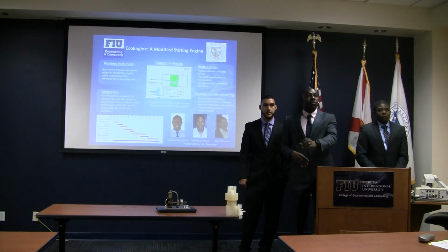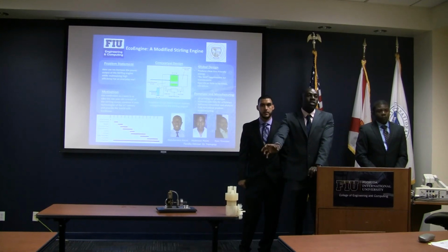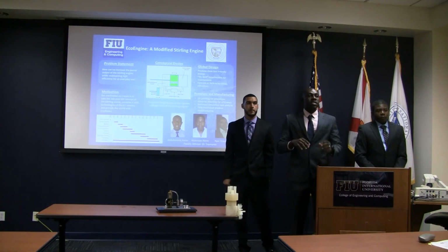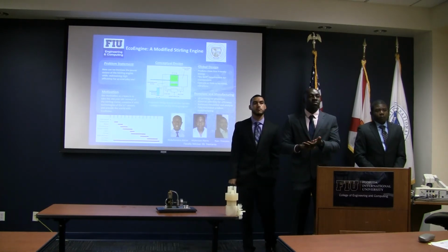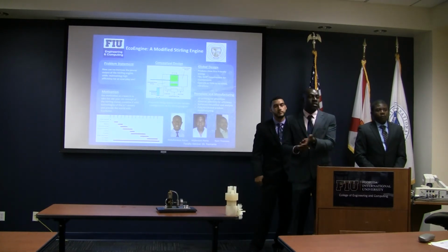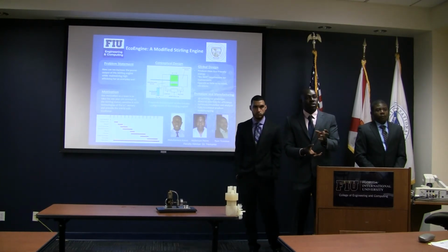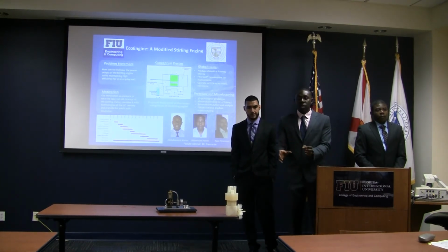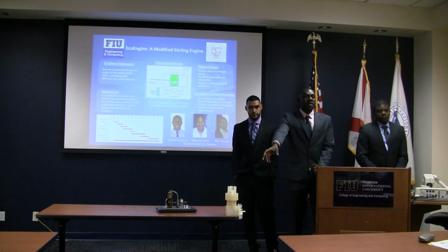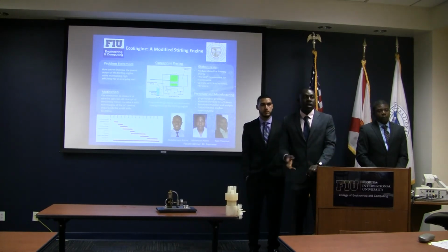We knew it would have improved it because, like I said, the regenerator is there to make it easier for the cylinders to get hot and get cold on time. With the change in temperature, we get more power. And the fan cools it down faster, so it gives more difference in temperature, which would have produced more power.